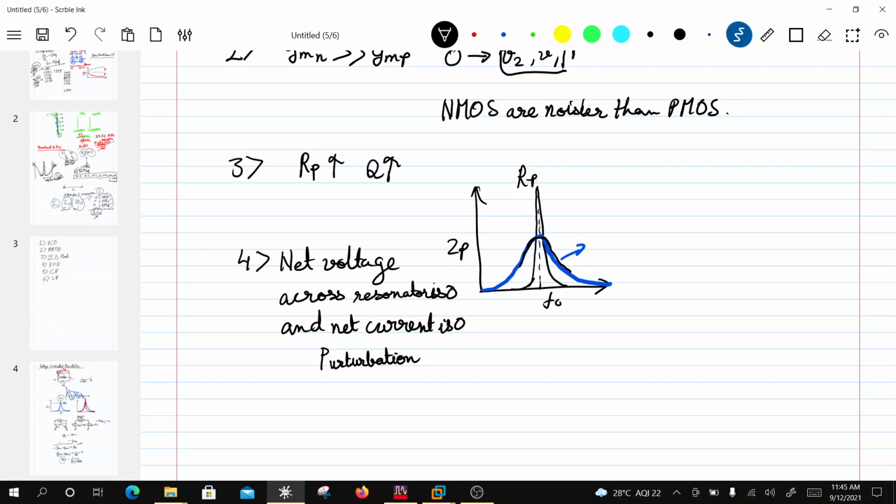So what I'm trying to say is, the circuit is going to perturb more if the Q is basically less, because this is being compensated by 1 over GMN and GMP, right? So you are using much larger transistors to compensate for a much smaller RP, right? You are using much larger transistors to compensate for a much lower RP, and that gives you a higher probability of perturbation. Perturbation is more here when you do that, versus when this is compensated by a small peak like that.